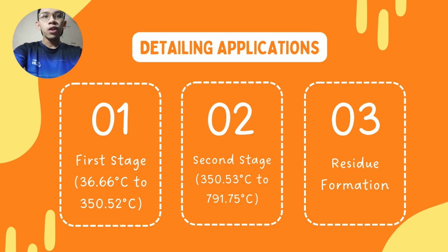The inflection point at 284.51 Celsius and the midpoint of 285.27 Celsius indicate the temperature at which the maximum rate of weight loss occurs for this phase. This stage represents the initial thermal degradation and loss of volatile impurities or additives. Second stage,